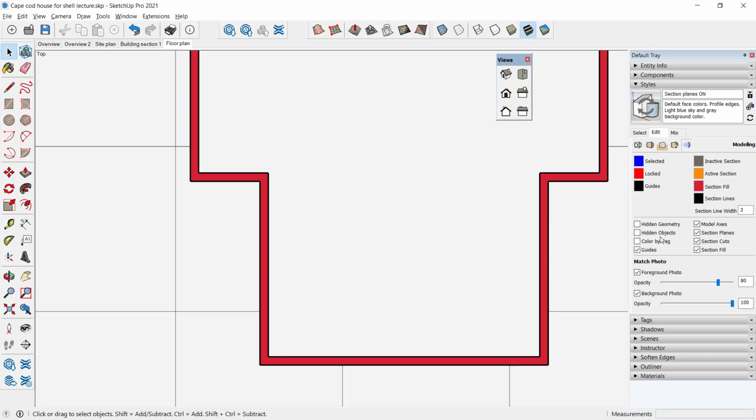You don't have to do that, and in all likelihood, we will be rendering our floor plans using a plug-in renderer, but for now, you can get a really cool look like that, and you can even control how thick the lines are that are defining the kind of boundary around the cut portion of the walls. And these changes, if you click the Recycle button in the Styles menu here, we'll just click Recycle.